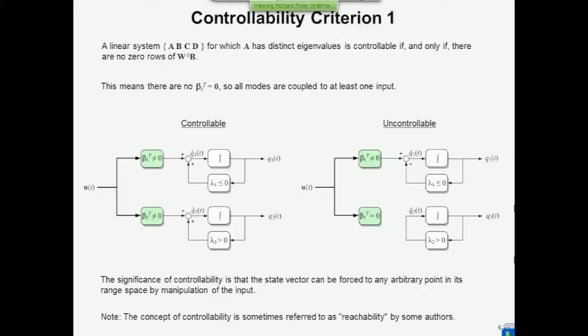It's not going to stay at 0. But you've identified the fact that you can't influence it through the input, and therefore, whatever happens to it, you can't change, and it is going to grow because there will be some disturbance which excites it, and then it practically grows. But mathematically, you're right. There is nothing to excite it, so theoretically, it would stay at 0 forever. But that's not reality. Is that okay?